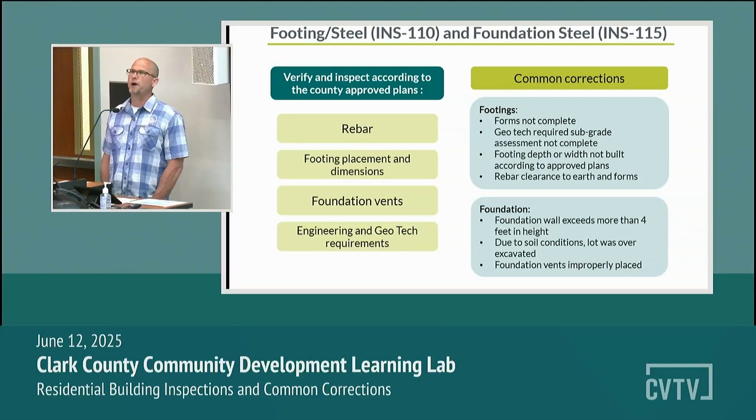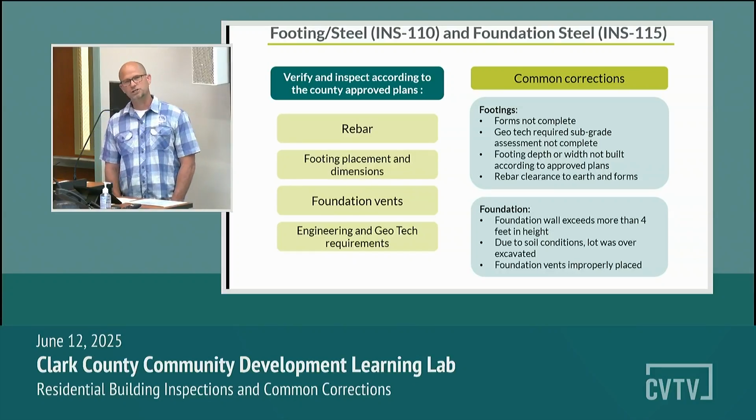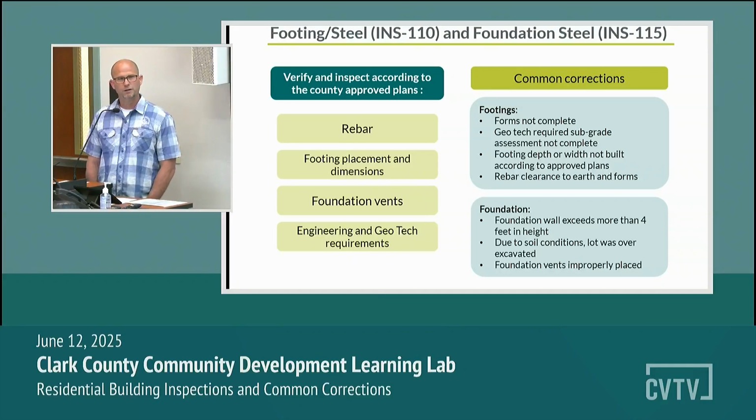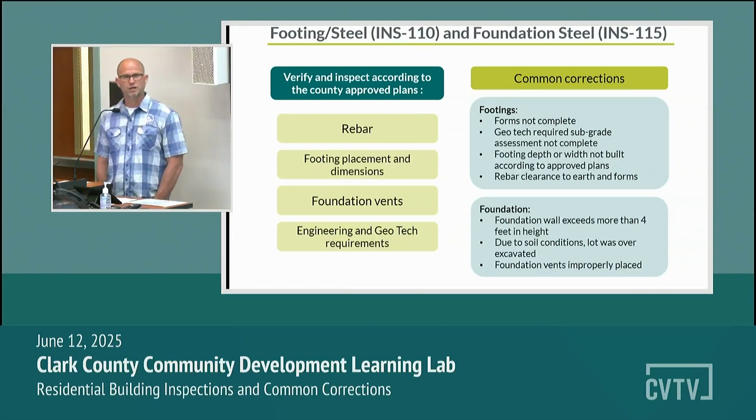Now this all might be in place. This all might be great. Your foundation guys did an amazing job. But unfortunately, if you don't have a geotech report, if it's required, we're going to have to fail the inspection. Now you might ask, well, what's a geotech report? A geotech is going to come out at the very beginning of the project when everything is still grass, still trees, and they're going to try to put together a report saying what the soils look like.